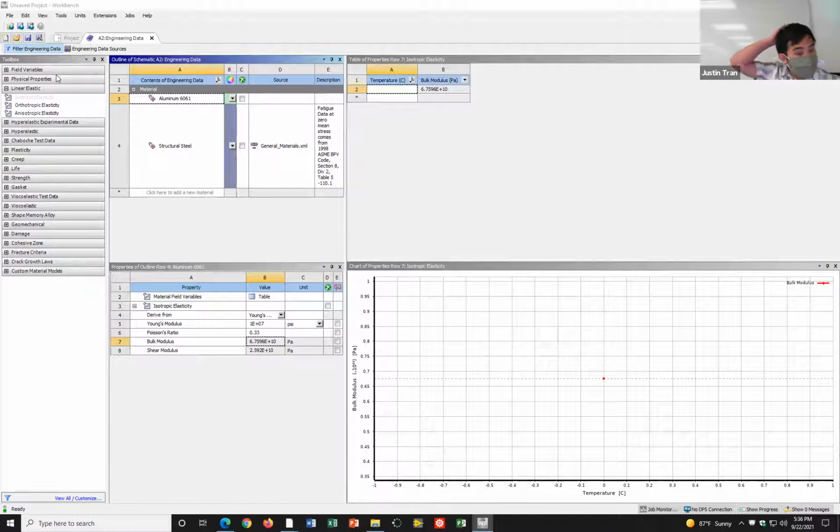Last activity, we stopped there at the Young's modulus and Poisson's ratio. But for this one, we need one more property, and that's the density. Remember what I mentioned before, that the weight of this sign is going to be significant, so we need to know the density of our material in order to properly compute its weight.